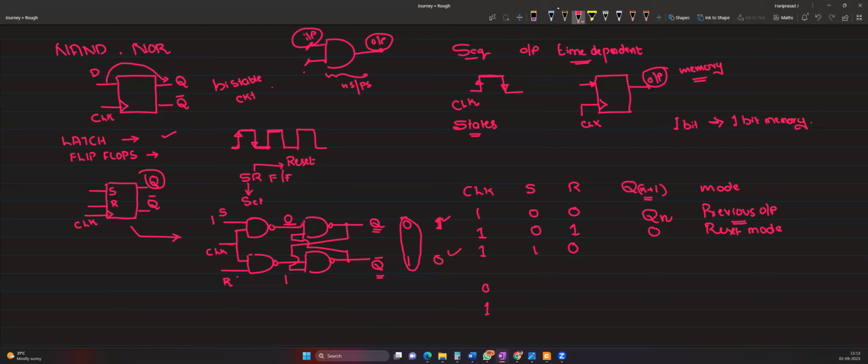Let me assume now it is 1, 0 only. In that case, 1 will be fed back to here. So irrespective of what the other states are, whenever the input is 1, 0, my output is forced to 1, 0. So this mode we call set. Clear? Yes, sir.